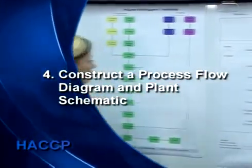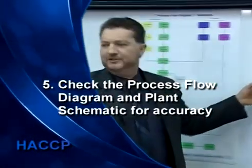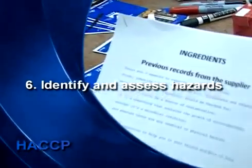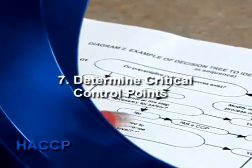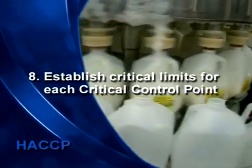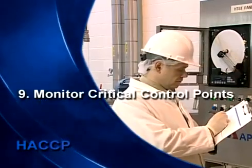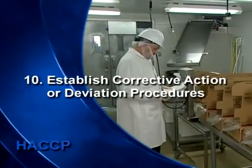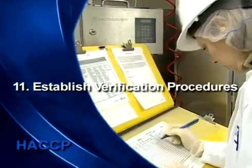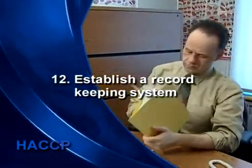Step 4. Construct a process flow diagram and plant schematic. Step 5. Check the process flow diagram and plant schematic for accuracy. Step 6. Identify and assess hazards. Step 7. Determine critical control points. Step 8. Establish critical limits for each critical control point. Step 9. Monitor critical control points. Step 10. Establish corrective action or deviation procedures. Step 11. Establish verification procedures. And Step 12. Establish a record-keeping system.